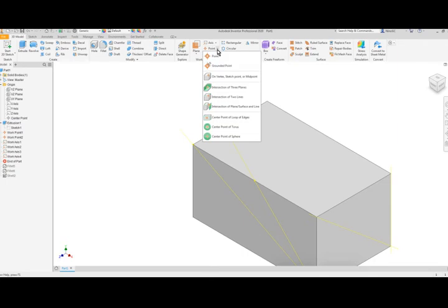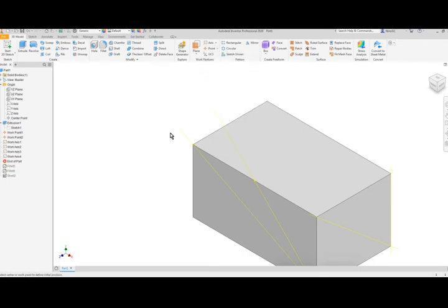The second of the work points is the grounded work point. The grounded work point commences by selecting a starting point, so I will select, say, that axis. And as we do that, it gives me the triad. The triad allows me then to select one of the three arrows. If I select the red arrow, that is associated with the x-axis. The blue arrow is associated to the z-axis, and the green arrow is associated to the y-axis.